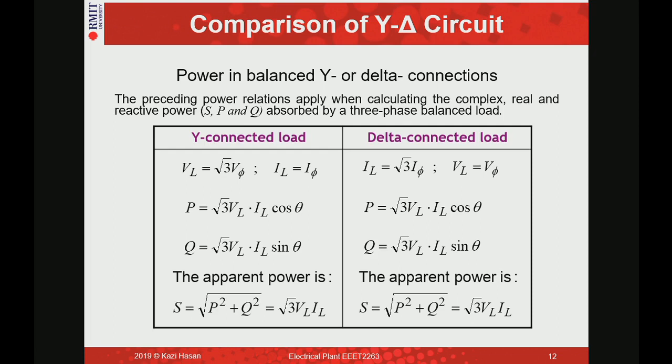So this is the line current we calculated, is it? Now in the power in delta connected circuits, that is only one phase, one branch. You're thinking about the whole system. That's why square root 3, and then when you square it, you get 3. Alright, thank you.